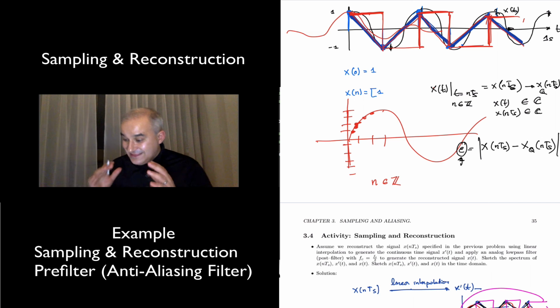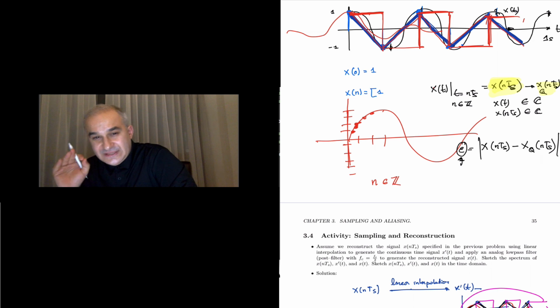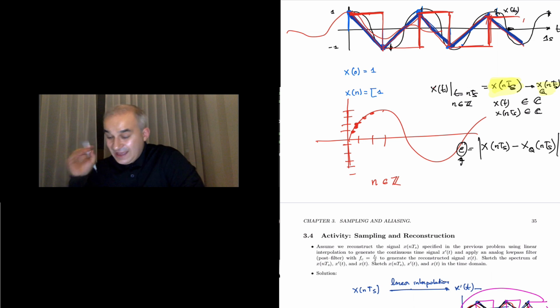That's it. This is the reason, by the way, why we are going to develop all the DSP theory using discrete time signals. The difference between the discrete time signal and the digital signal is just that you quantize it. And so it's a small change, perhaps a small error. And remember that error, you can make it as small as you want by increasing the number of bits.